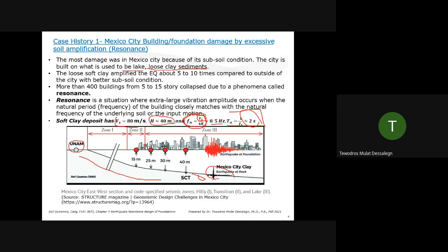We usually work together, right? Because it's a big project, everybody is usually involved: geologist, geotechnical engineer, seismologist, seismic engineer, and structural engineer. Everybody works together. Then this is your input to the structural engineer: Hey, I have this kind of soil, and I may have a resonance, so I'm not recommending this type of building on this site. If we have to do it, then let's make sure the structural engineer gives you the fundamental period or fundamental frequency of the structure. It's easy to determine.